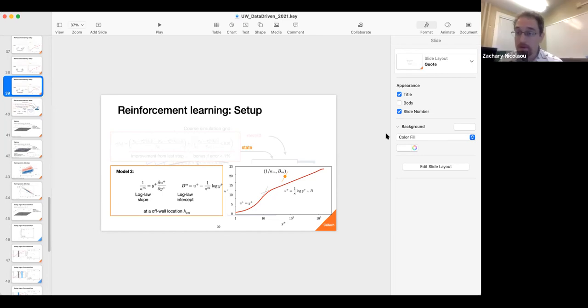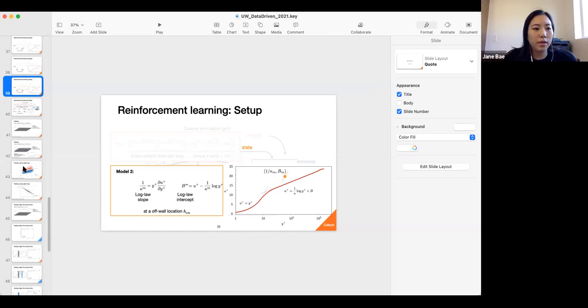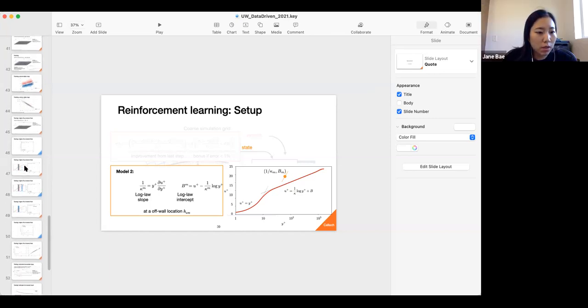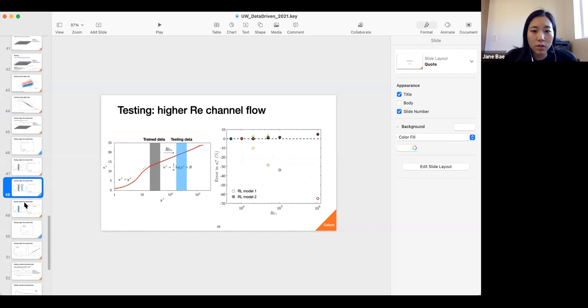Great, quick one. So we're almost done here, a couple more questions, and then I'll check the YouTube if we have time. Rod Hagi says, thanks for the presentation. How does the change in the grid size for high Reynolds affect the computation cost? Yeah, so I'm assuming you're talking about this case where if we do grid refinement, we see improved results. Here, I'm only refining in the wall normal direction.